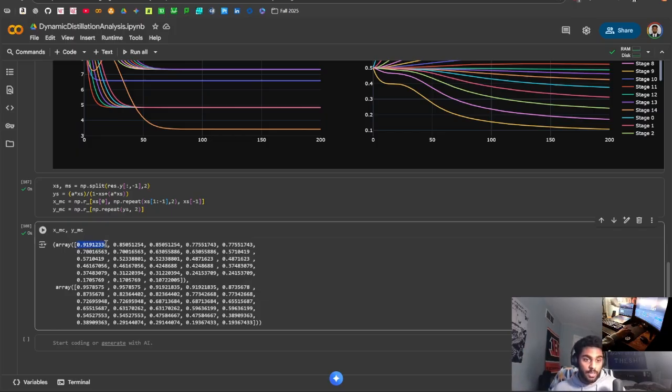So this is our distillate composition. Then we go over and hit this x value. However, our y stays the same. So this is our first step over, hitting our equilibrium line. Then we drop, staying at the same x. And since they're offset, we create our staircase in this way. So realistically, this is our McCabe-Thiele staircase.